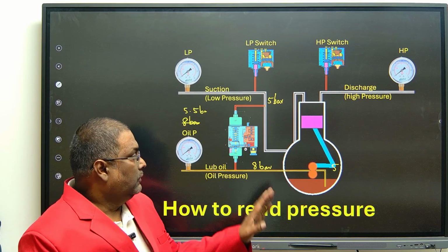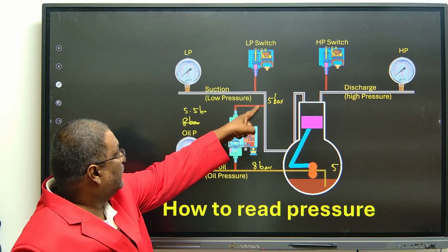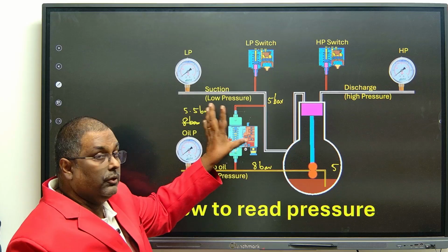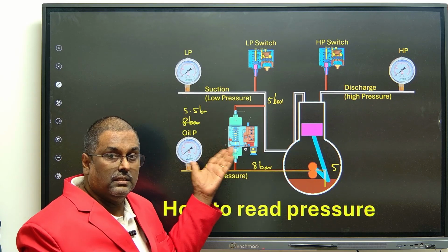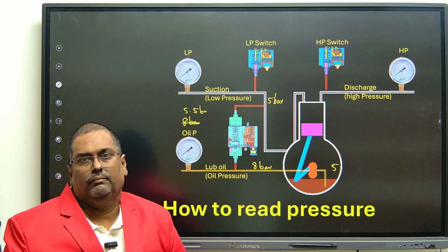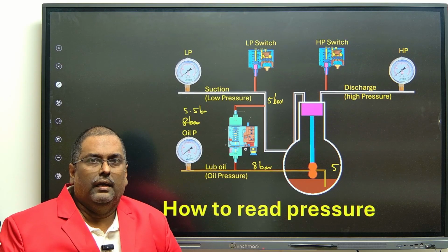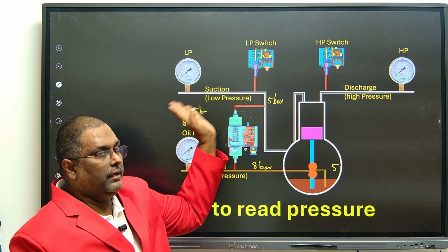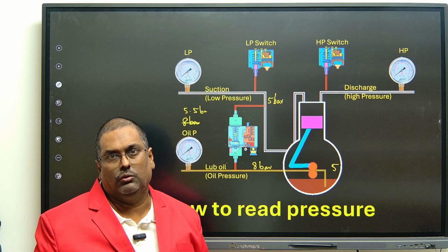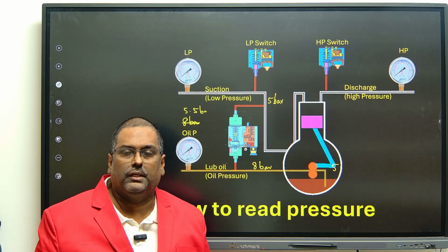Okay, so now you got the idea how it is connected, and the connection you see here, the suction line is given here. If you are onboard sailing in the ship, you check this; the system will be like this only. Normally we don't know everything inside the panel and only the gauges are outside. Junior engineers take the readings, see 3 readings and directly write them in the logbook. Seniors, please check like this and then confirm the lube oil pressure is okay.